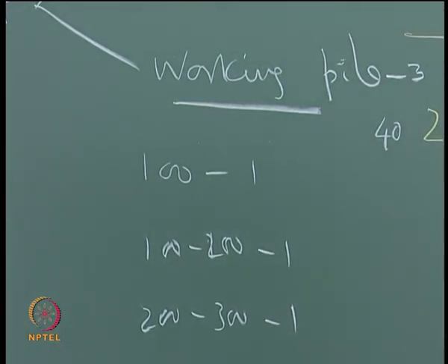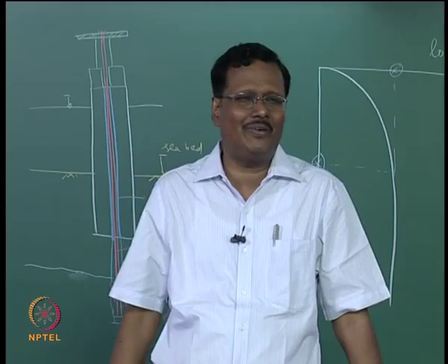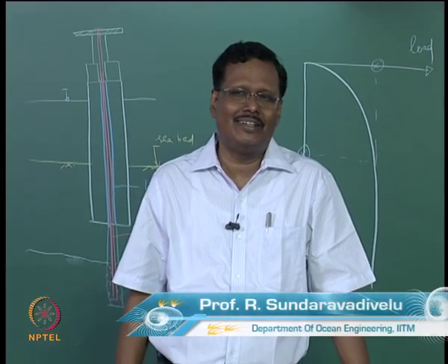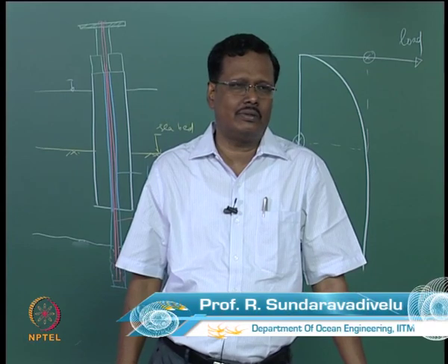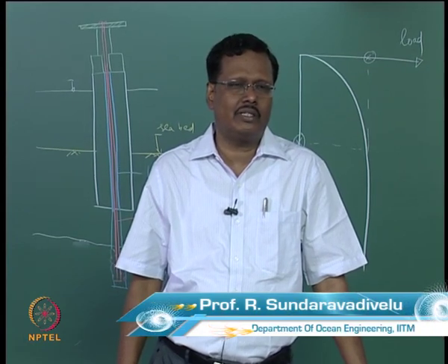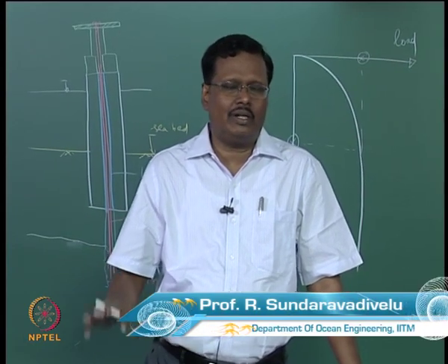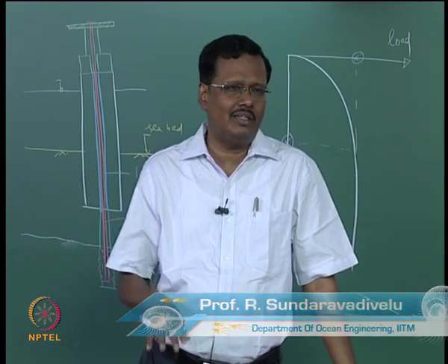after everything is over. They have done that for Perambur flyover and they found a lot of problems. After completing all the piles you cannot do it. So you have to do the initial pile load test. Initial means before driving any working pile you have to do the initial pile load test.